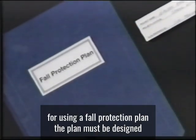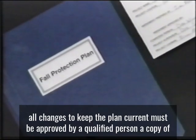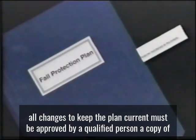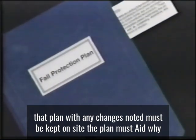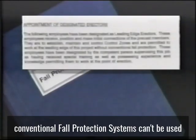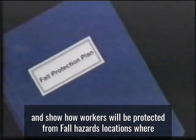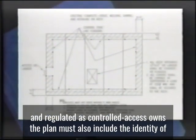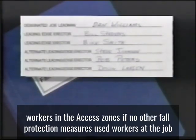The plan must be designed for each specific worksite by a qualified person. All changes to keep the plan current must be approved by a qualified person. A copy of that plan with any changes noted must be kept on site. The plan must state why conventional fall protection systems can't be used and show how workers will be protected from fall hazards. Locations where conventional fall protection systems can't be used will be classified and regulated as controlled access zones. The plan must also include the identity of workers in the controlled access zones.